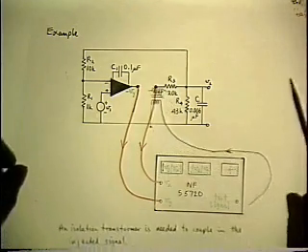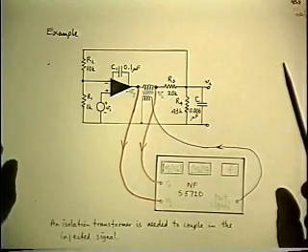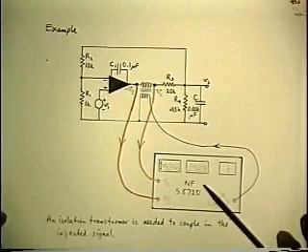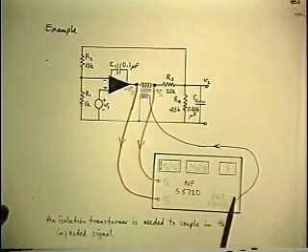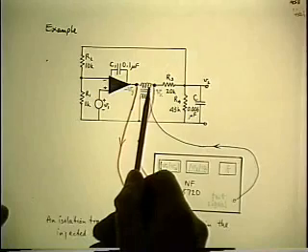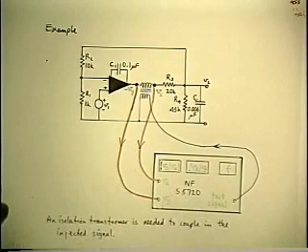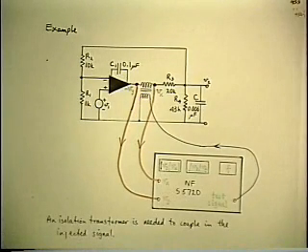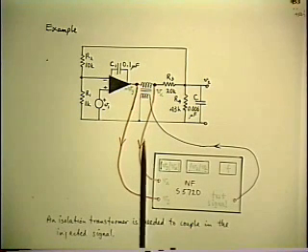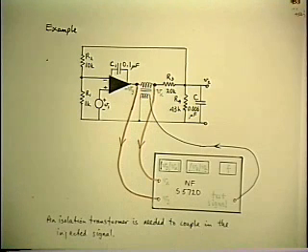So what you visualize is that you need an isolation injection transformer, which basically converts a single-ended source into a floating output. And that's all right in principle, but then when you try to do this, you look into your box full of discarded components looking for a transformer, and of course you don't have one because you've never used one.